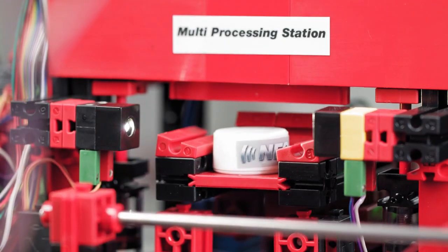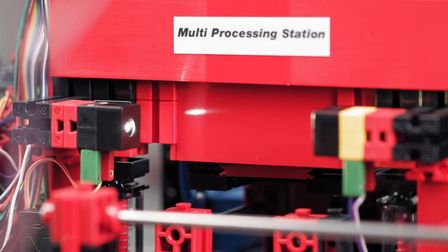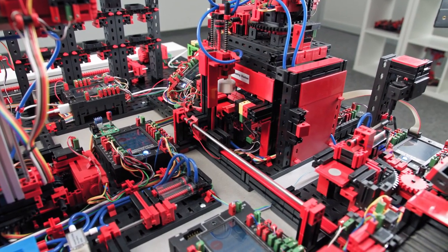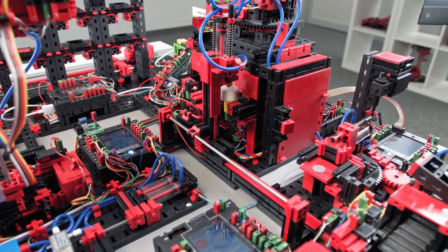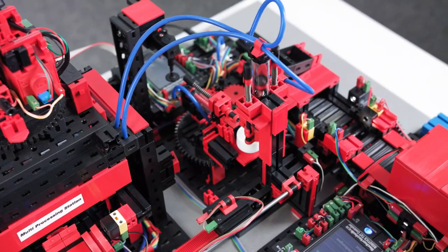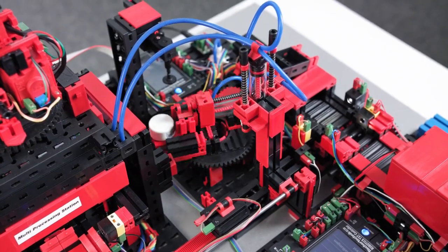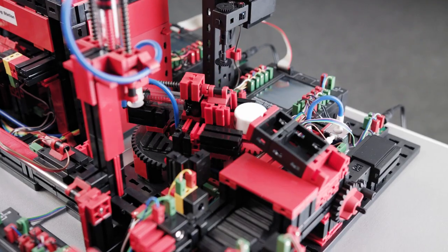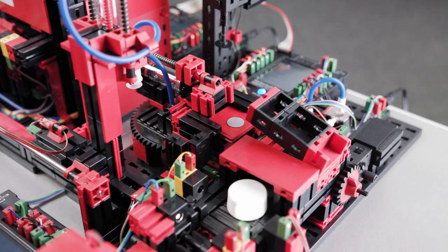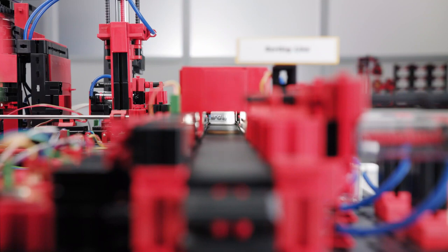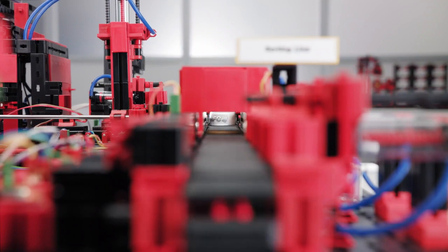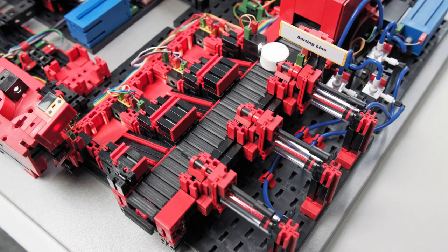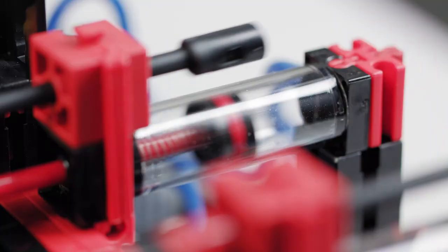The production process is simulated in 2 steps. The suction gripper passes the material on from one step to the next. The material is transferred to the sorting system once production is complete. The sorting system receives the allocation command as soon as the color sorter detects the proper color. The material is sorted using pneumatic cylinders.